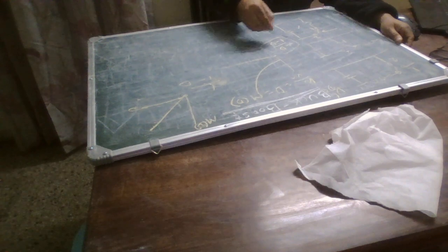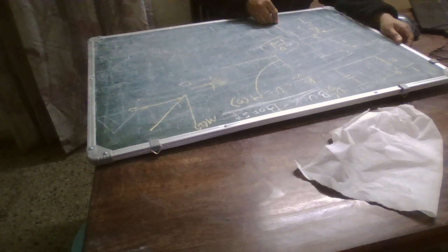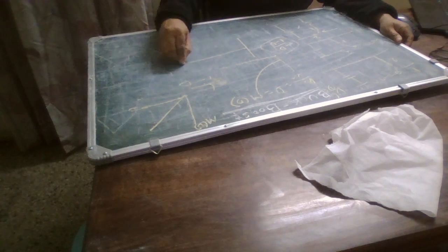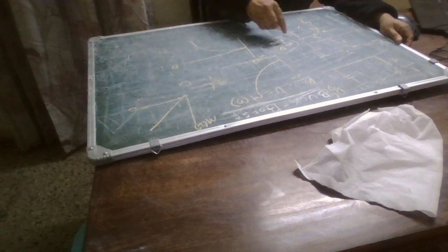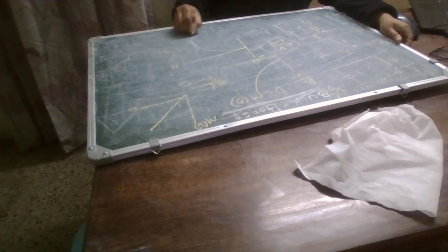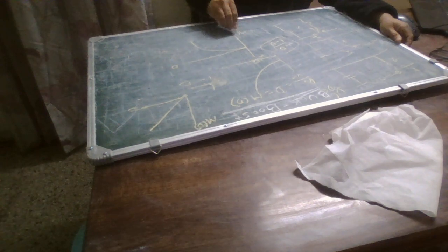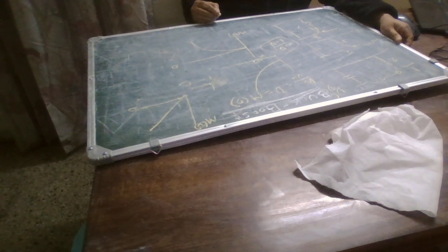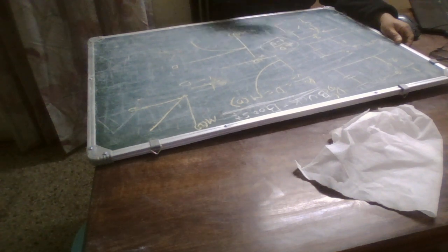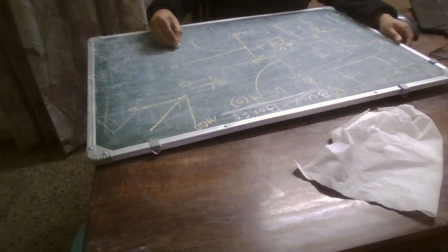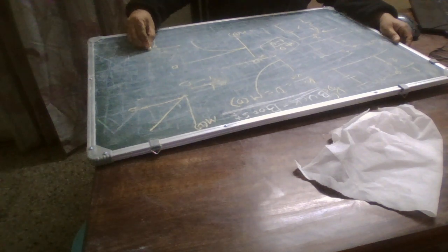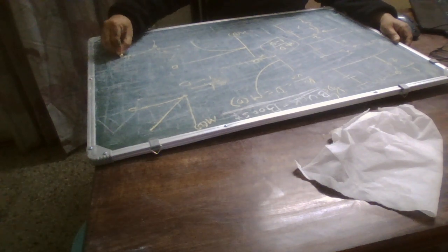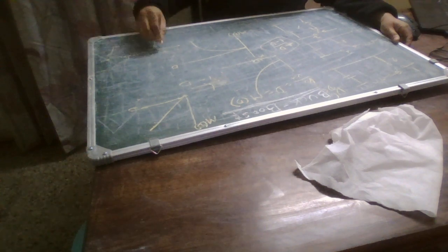Just in brief, I want to bring into notice that this is the duty cycle axis, this is the conversion ratio axis. Because of this negative, it's falling down. This is minus D upon 1 minus D only. And if I am taking a non-inverting configuration, that means I am getting the conversion ratio as positive. In that scenario, the circuit configuration would be this way, 1, 2.